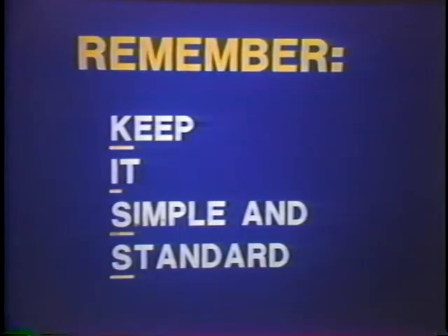Now you can see here an example of an inventory form developed by one jurisdiction. Inventory numbers or serial numbers are sometimes used on signs. When they are used, the numbers are placed on the back of the panel so that the numbers don't interfere with the sign's message. The primary rules of signs are that 1. They should be simple, and 2. They must be standard. Working in conjunction with signs to guide motorists are roadway marking and delineation.